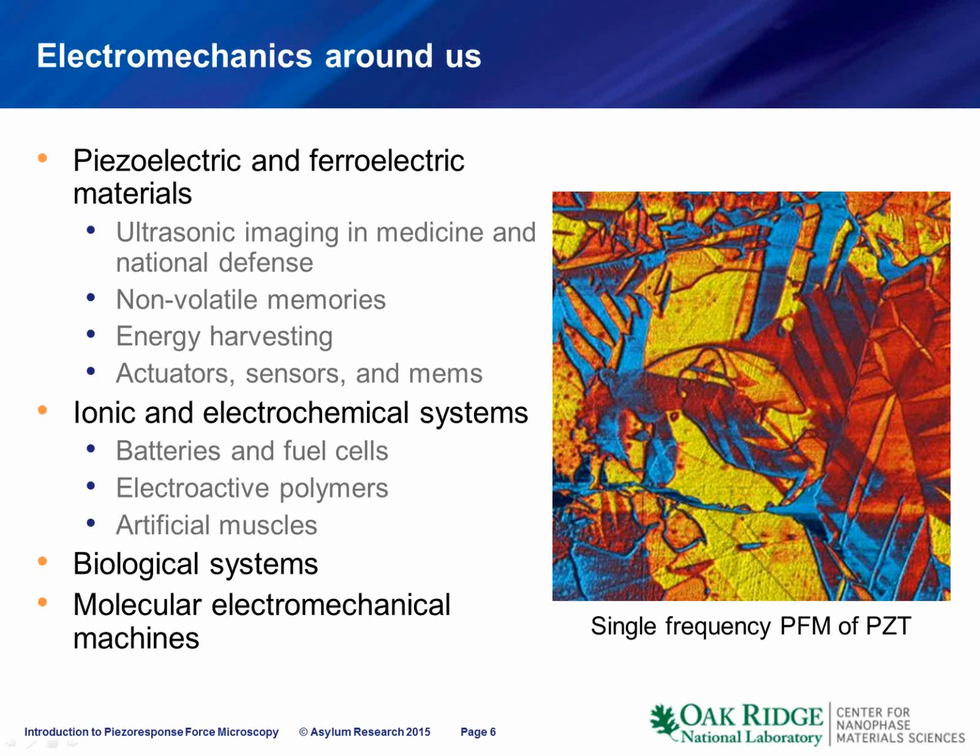The answer is it's extraordinarily universal. So there are multiple applications for basic piezoelectric and ferroelectric materials. So these include ultrasonic imaging in medicine and national defense, for example, sonars. There are multiple emergent applications such as non-volatile ferroelectric memories, energy harvesting, actuators, sensors, microelectromechanical systems. So these are all applications of piezo and ferroelectrics.